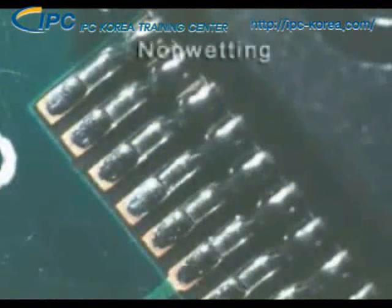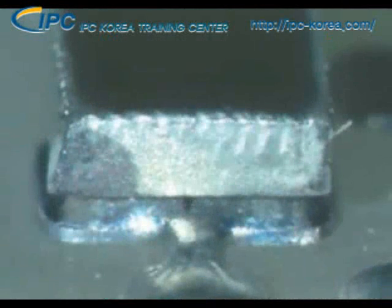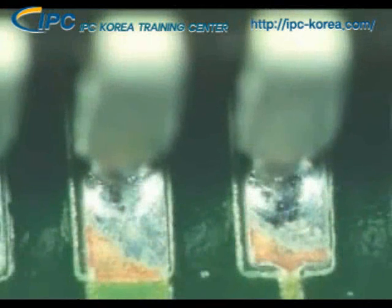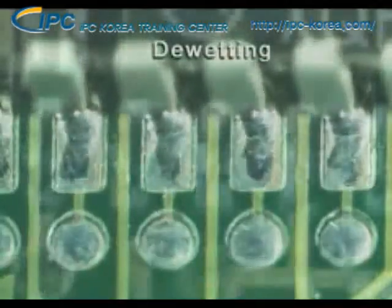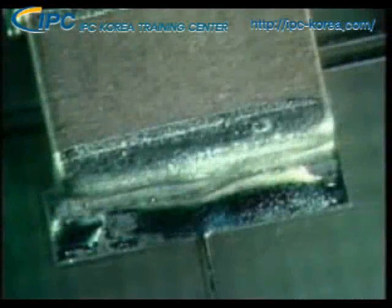Now let's look at non-wetting. Notice that the solder has not adhered to either the termination or the land. Non-wetting is a defect for all types of surface mount connections. De-wetting occurs when molten solder coats the surface, then pulls back, leaving only a thin film of solder covering the land in some areas and irregular mounds of solder in others.